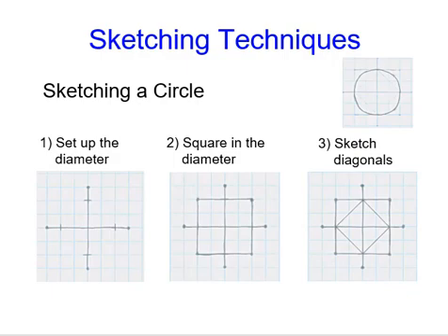To sketch a circle, you will complete a 5-step process. In step 1, you create a horizontal and vertical line the size of the desired diameter of the circle. Make sure the 2 lines intersect each other at the midpoints, or the midway across that line is the midpoint.